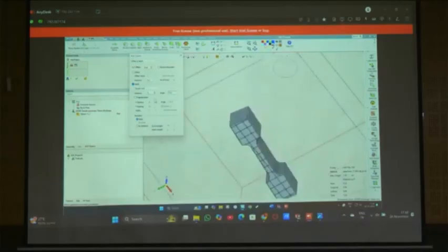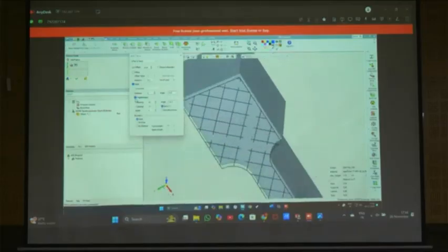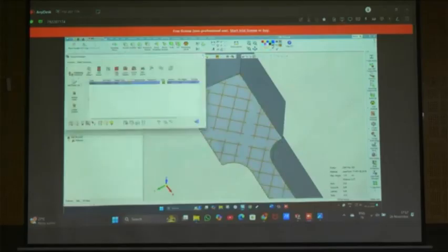See, and square grid or something we can take, and I will keep distance 2 so that we get more. Square shell. Usually prefer cross line or square grid. Fragmentation means if you apply fragmentation, there are some gaps, so that we can easily break the support, and we can reduce the post processing time. This is one of the techniques, fragmentation. So we can apply this pattern. Now we can go with the wall support.